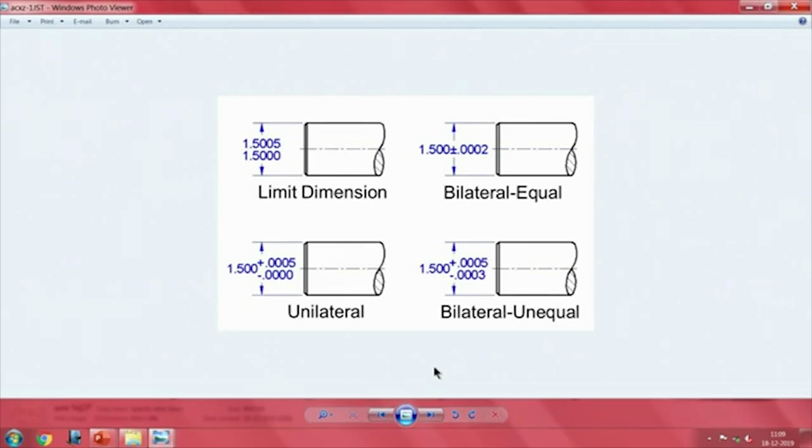if you remember the earlier thing, much earlier I mentioned there is a limit in this, no? The shaft happens to be 0.005 nominal units. Beyond this, the lower limit shows the limits with which the shaft can be accepted. A lot of it depends on the method of manufacture, and even if you start with a machining device which has the correct settings, with the wear and tear of the tools or the temperature variations and all that, small variations will occur.